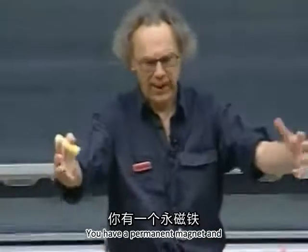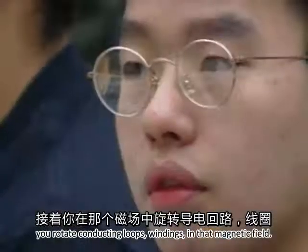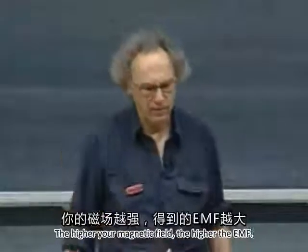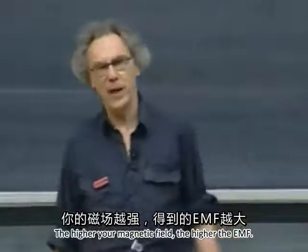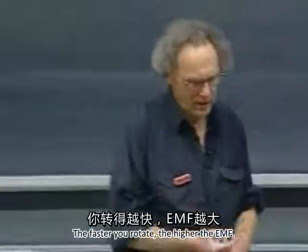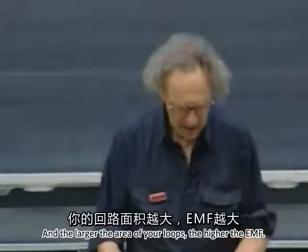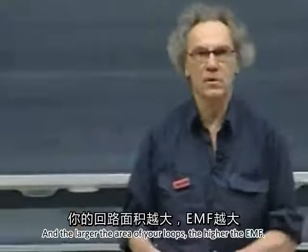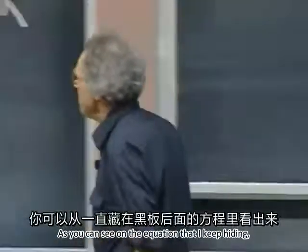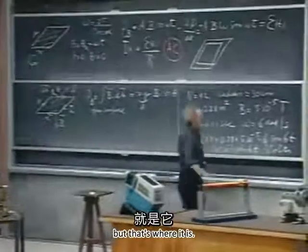You have a permanent magnet, and you rotate conducting loops, windings, in that magnetic field. The higher your magnetic field, the higher the EMF. The faster you rotate, the higher the EMF. The more windings you have, the higher the EMF. And the larger the area of your loops, the higher the EMF. As you can see on the equation that I keep hiding. That's where it is.